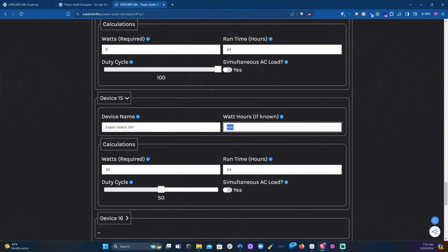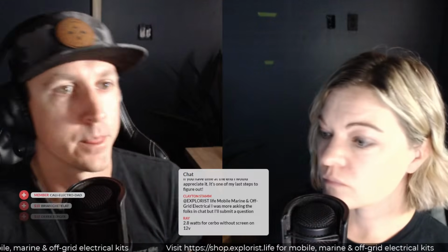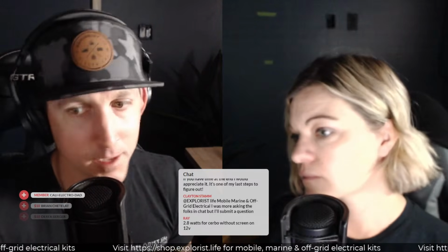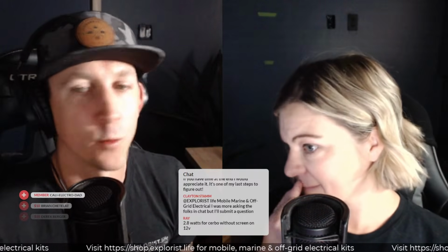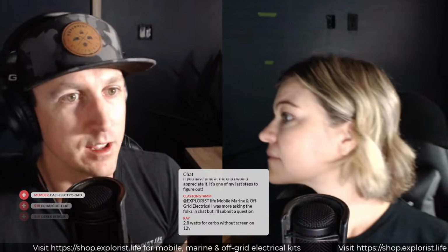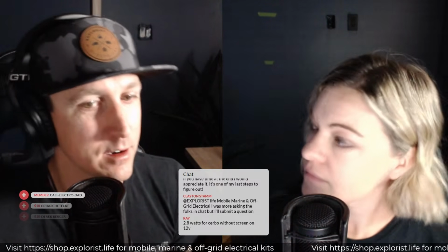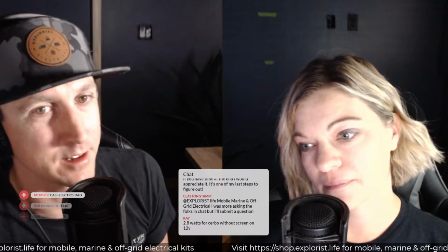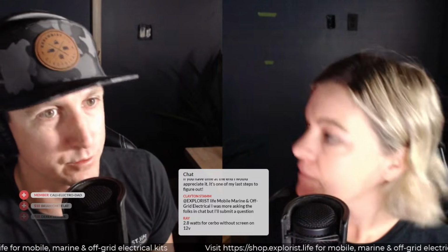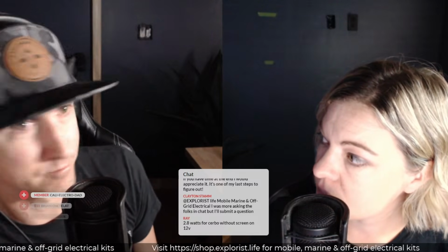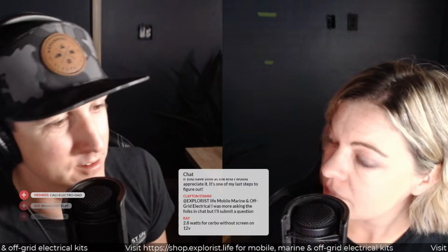Now, a thing about the heaters is, heaters take a fair amount of power to power up. They may take, let's call it 200 watts for 1 minute while the unit is powering up. But realistically, if something happens for just 30 seconds or 1 minute, it's a little bit of an increased load for that short of time. It sort of doesn't matter in the overall power audit scheme.